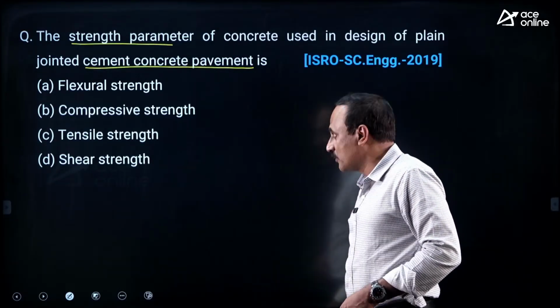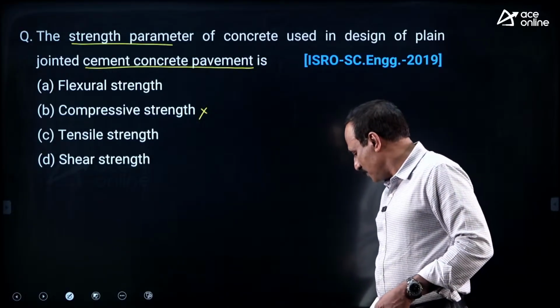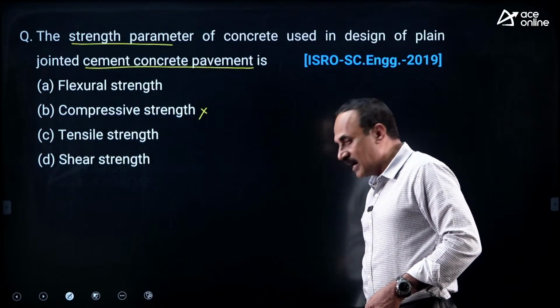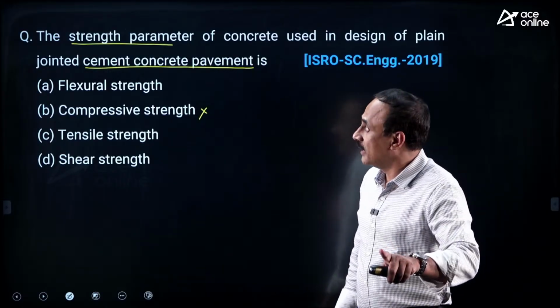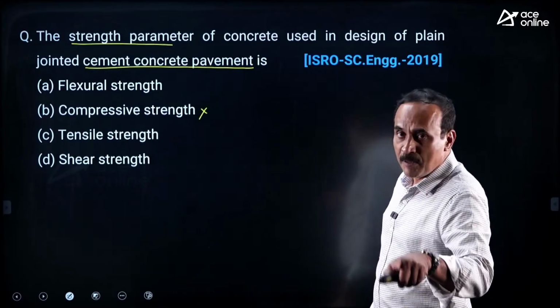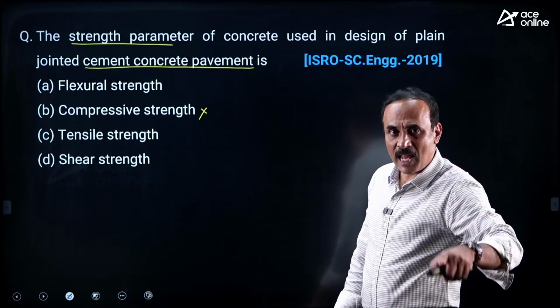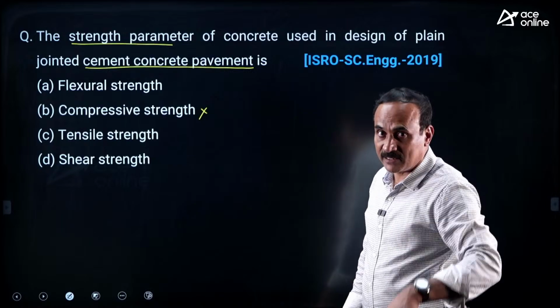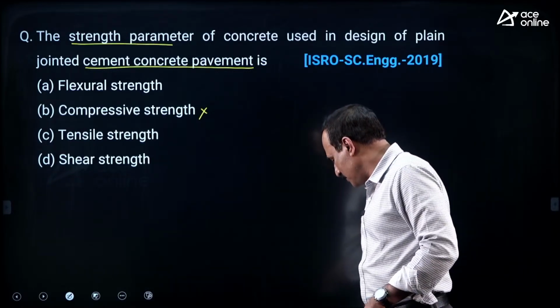Obviously, it is not compressive strength, because in flexible pavement, Murali, it is not the compressive strength. In cement concrete pavement, rigid pavement, load transfer is by slab action or flexural action or bending action. Based on this point, you give me the answer, Murali.